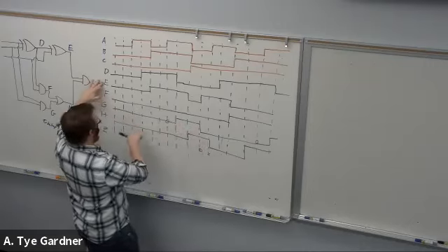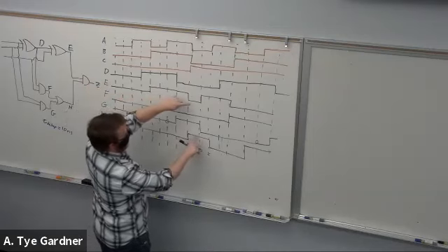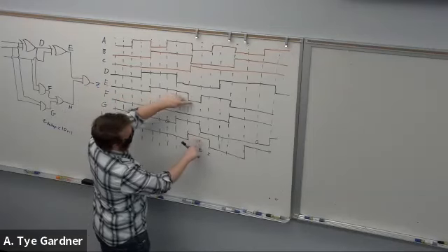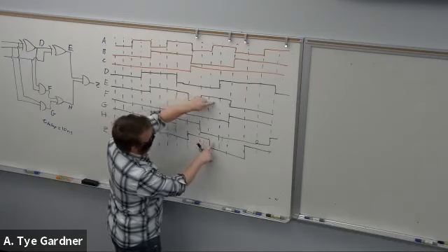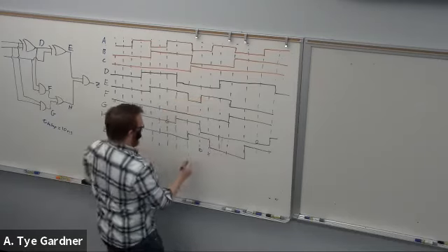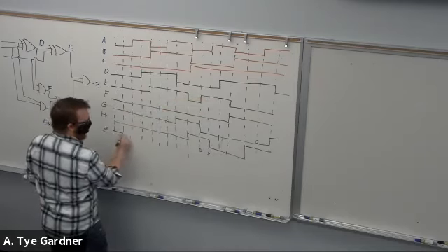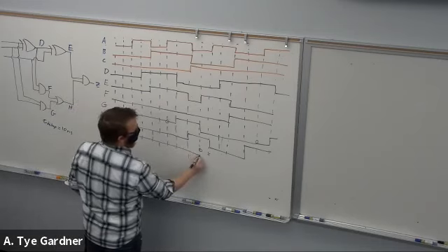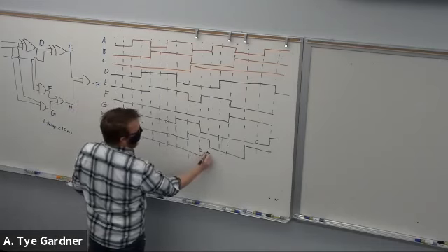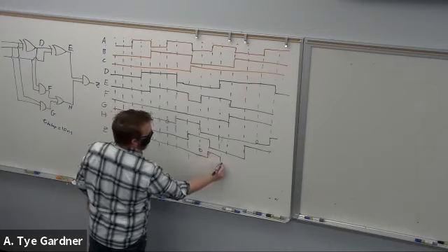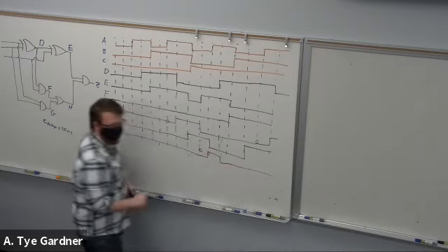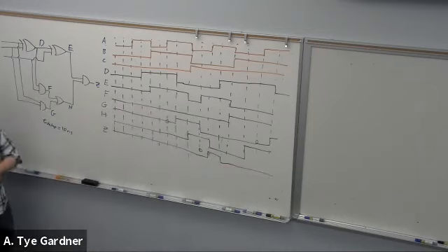H and E is true here, false there, and that's it. A 10 nanosecond delay, it rises, goes false. And that's the right combinational timing diagram.